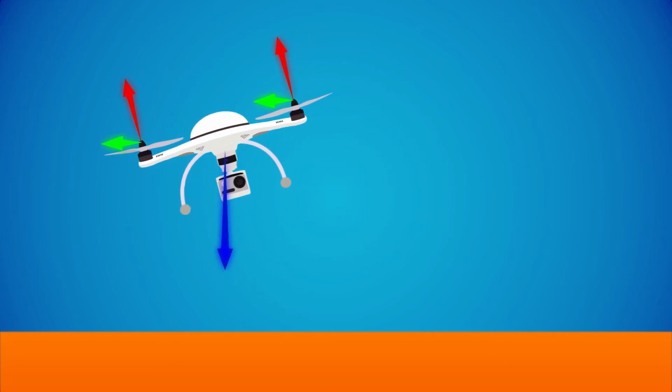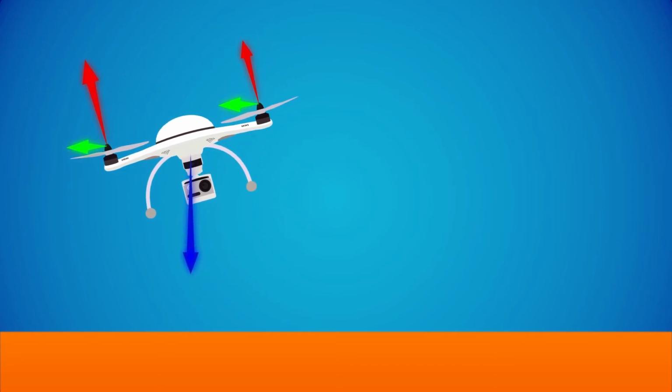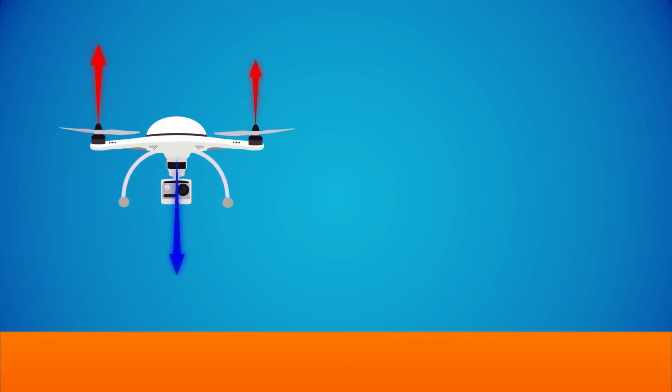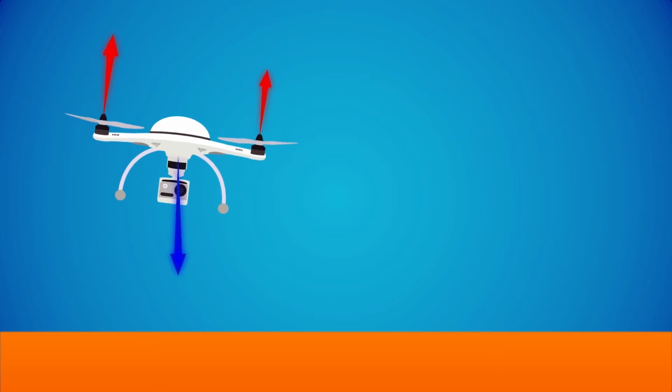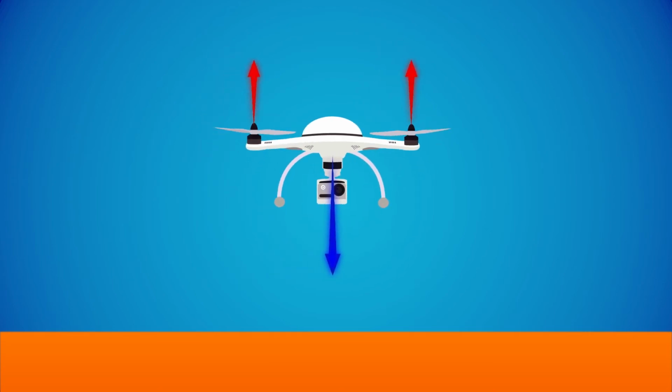To counteract that, we measure this tilt using sensors much like the ones in your smartphone and command one motor to generate more thrust than the others, moving it back to the original angle. And if we wish to move horizontally, we simply generate this tilt ourselves and move it where we want.